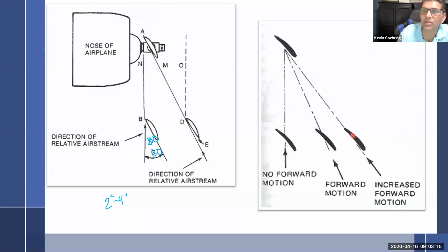And I have a nice 2 to 4 degree angle of attack, which I guess I could tell you all that to tell you, if you think it through, this propeller that is a fixed pitch propeller and the pitch never changes really is only going to work very well and very efficiently in a very narrow range of operation. The RPM must be at the exact designed RPM while the aircraft is moving forward at the exact speed that the aircraft was designed to move forward in.